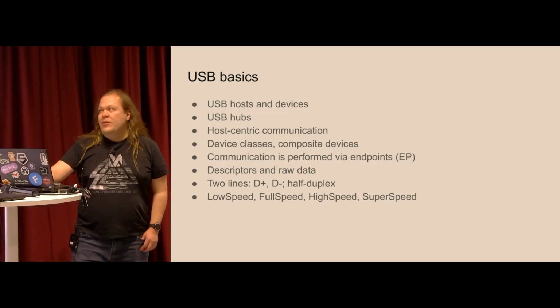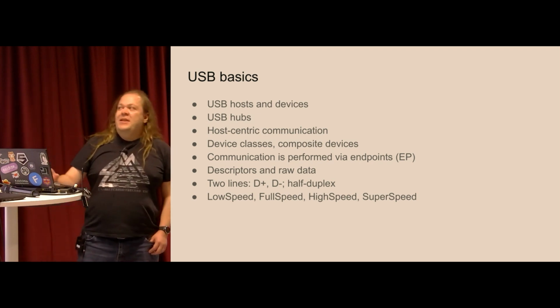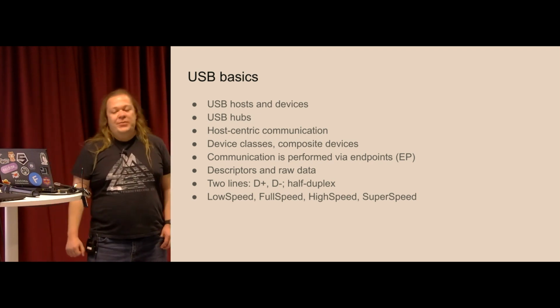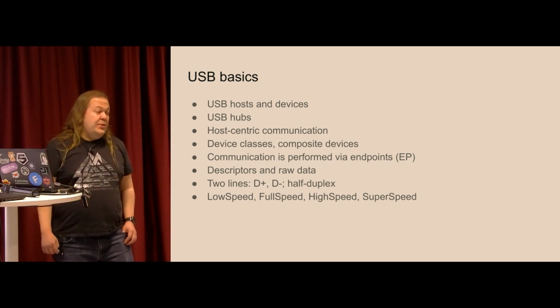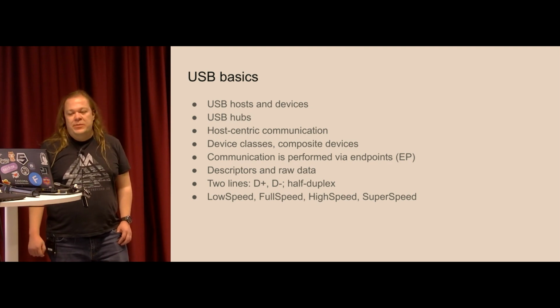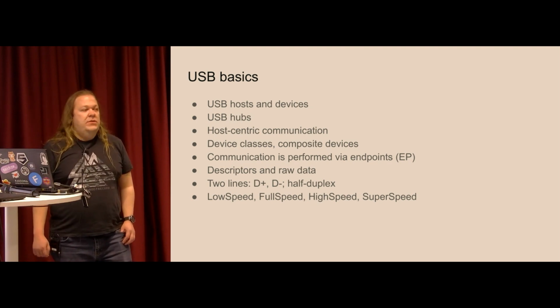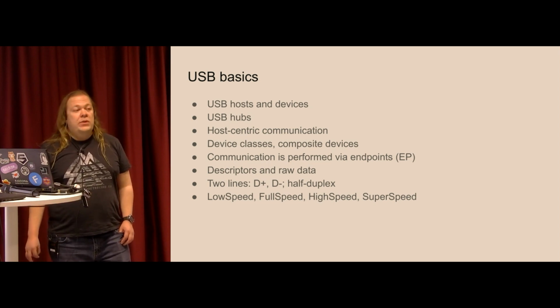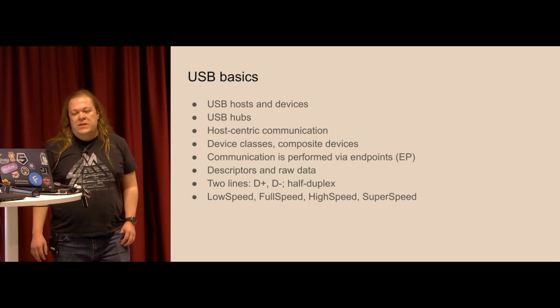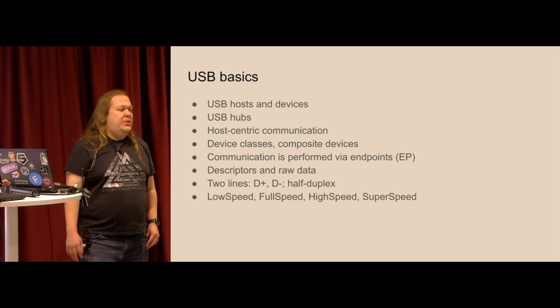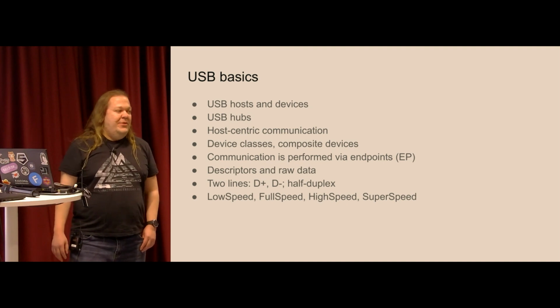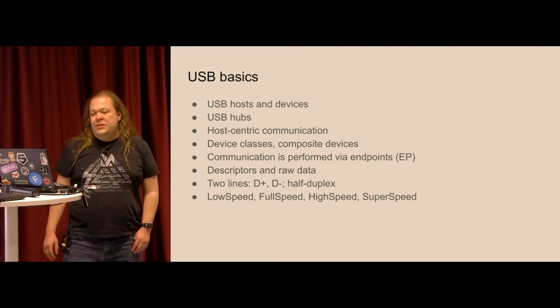For the rest, or in general, I will go through some USB basics on a single page. So USB is a relatively simple protocol. It has USB hosts and devices concepts, and hosts are the main component here, which initiates all the transfers, and we also have USB hubs to multiply the number of devices we can connect to a single host.